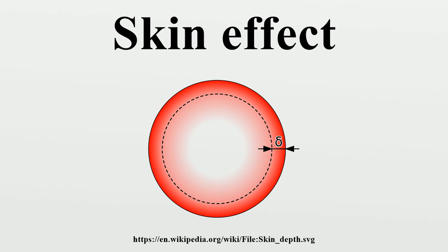Note: the heat-dependent manufacturing process for wire results in oxidation of the surface in the finished product. Therefore, the conductivity of the skin is significantly less than the underlying unoxidized base metal. It is to be expected that unless the oxidized surface material is removed, some loss of performance from the theoretical model will occur.